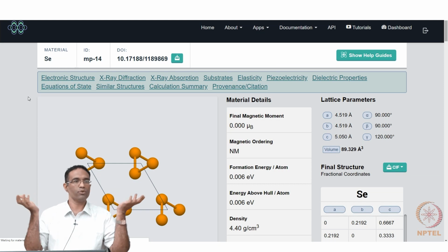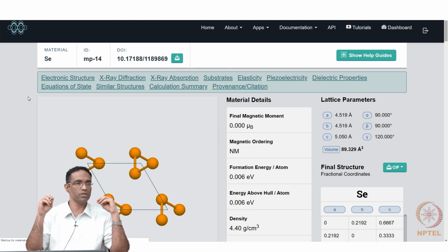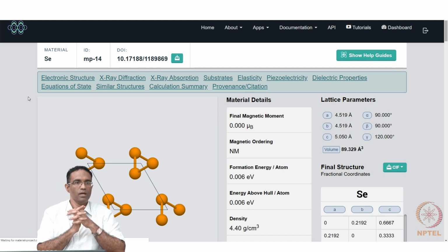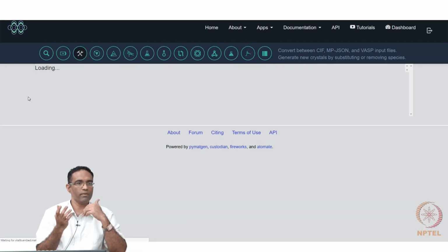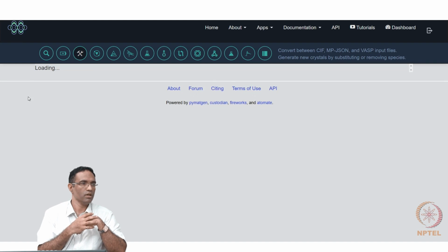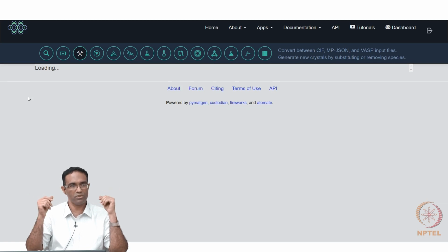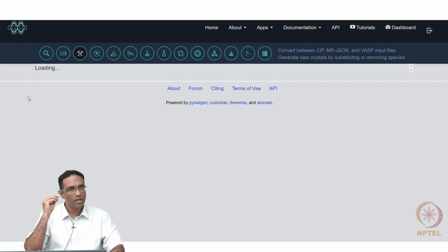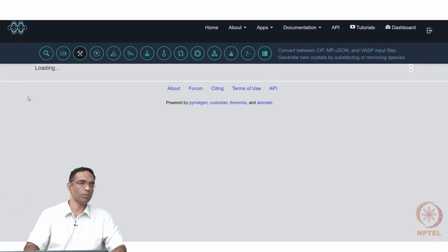One of the first things that you will be doing whenever you are running molecular dynamics simulations is to create the crystal structure. Not always are crystal structures BCC or FCC, for which you can get away with writing some simple codes. When they are monoclinic and tetragonal, you have to be careful, and when each unit cell contains a large number of atoms, it becomes extremely important for you to generate these structures correctly, and also check them. You can create a unit cell in MATLAB, check it, and use that to generate your crystal structures for the molecular simulation package that you are going to be using.